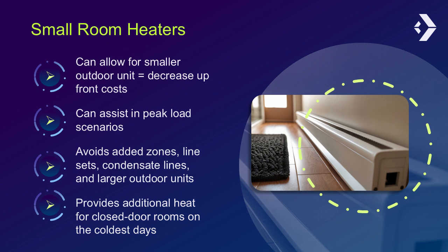Small room heaters aren't a one-size-fits-all solution, and there's certainly not a reason to skip installing a heat pump head where one is genuinely needed. This approach works best for very small, low-load rooms. Think small bedrooms or offices. It's not the right fit for every home or every room. Always consider the space, the load, the airflow, and the homeowner's comfort expectations when deciding if this is the right solution.